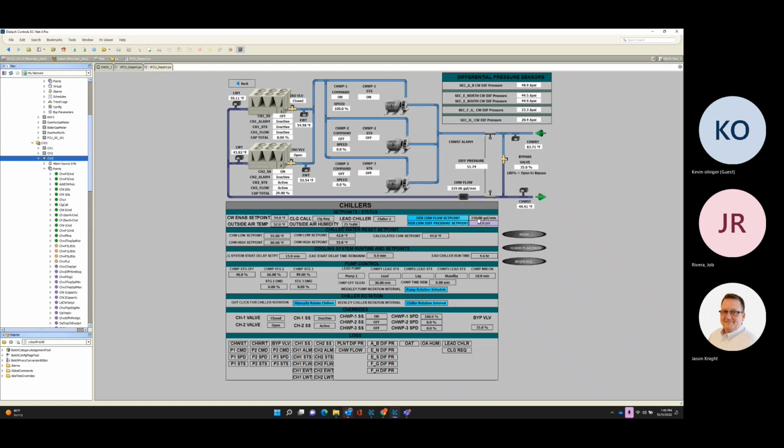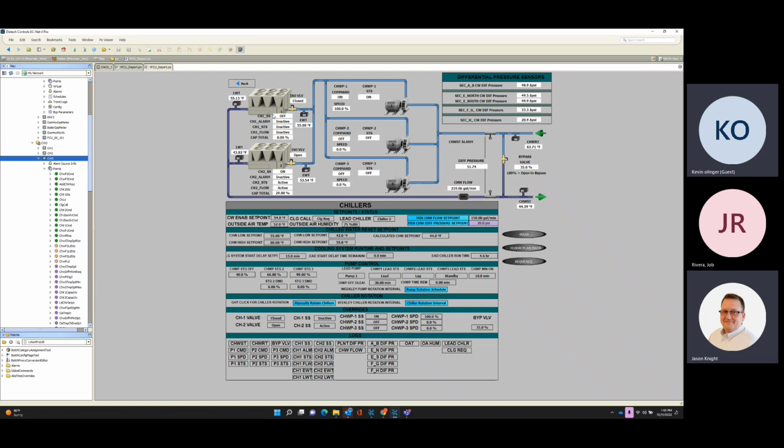And so a week and a half ago, we had a couple intermittent trips, and I went back and started looking at all my valve positions, and everything was shutting down. Like our air handlers were economizing, the DOASs were bringing in cool air. And it might have been 2 weeks ago, but when we first saw that, it's like, oh man, my chiller started tripping because I was pushing water out to the building, but yet it wasn't enough. And so we were trying to massage that in, and the valve at 35% is eliminating all these nuisance trips.